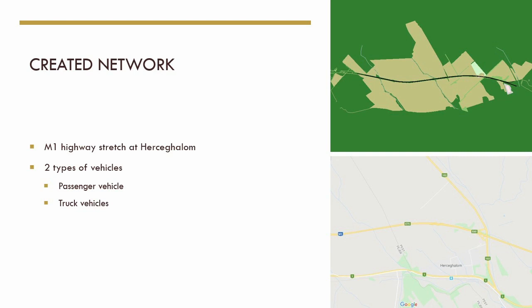The other type of vehicle is the passenger vehicle. For this we set a 1 meter per second square acceleration, a 4.5 meter per second square deceleration. The length is 5 meters and the maximum speed is 130 km per hour. Here we also define two flow types, 5000 vehicles per hour for the main flow and 1000 vehicles per hour for the RAM flow. These can also be found in the passenger trips XML file.